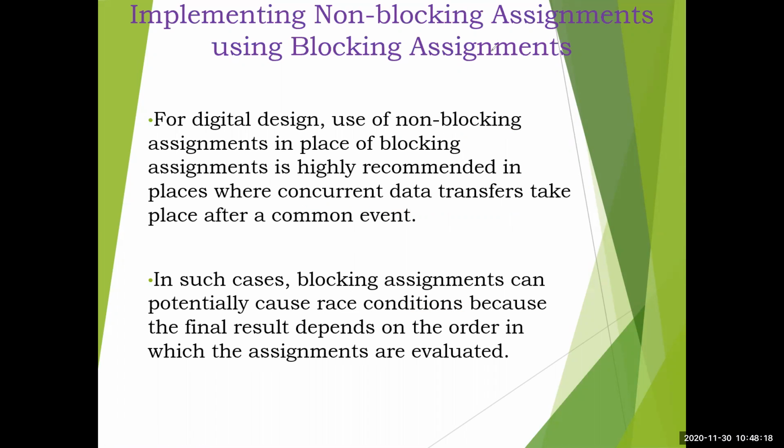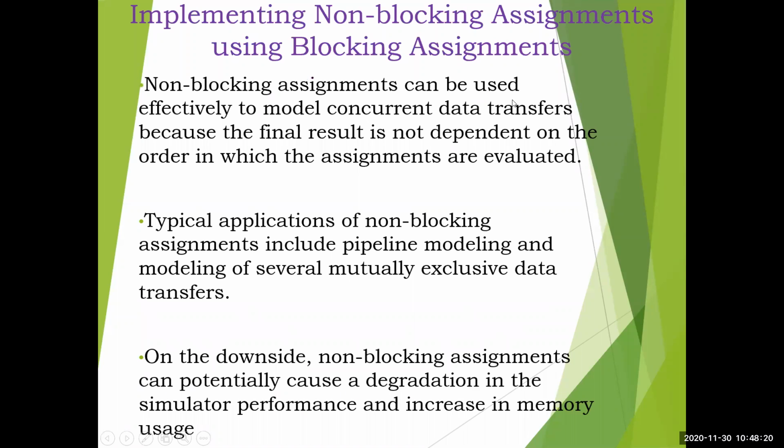Non-blocking assignments can be used effectively to model concurrent data transfers because the final result is not dependent on the order in which the assignments are evaluated. It is split into read and write operations, and because of that the problem is solved. Typical applications of non-blocking assignments include pipeline modeling. In microprocessor architecture, you have learned about pipelines, and to model that, non-blocking assignments are used, as well as in modeling several mutually exclusive data transfers.